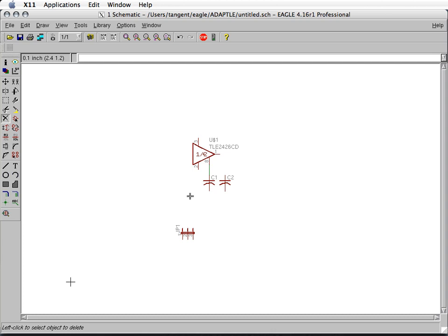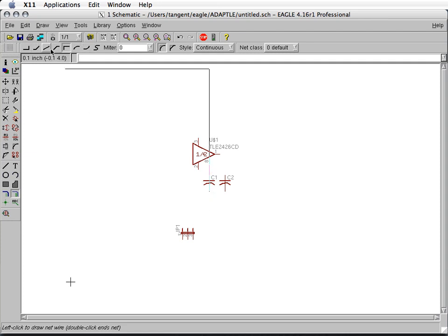And so I'm going to delete those 3 pieces of the net, and I'm going to go back into net mode. And so I showed you that I could click and click and click, and that will work. Another way you could do this is kind of watch that wire. I'm right clicking now, okay? And what that's doing is it's toggling among the bends. You can watch up here as well, these icons will do it too, and you can click on them, but I find it simpler just to watch the wire while I right click until I get the bend I want.